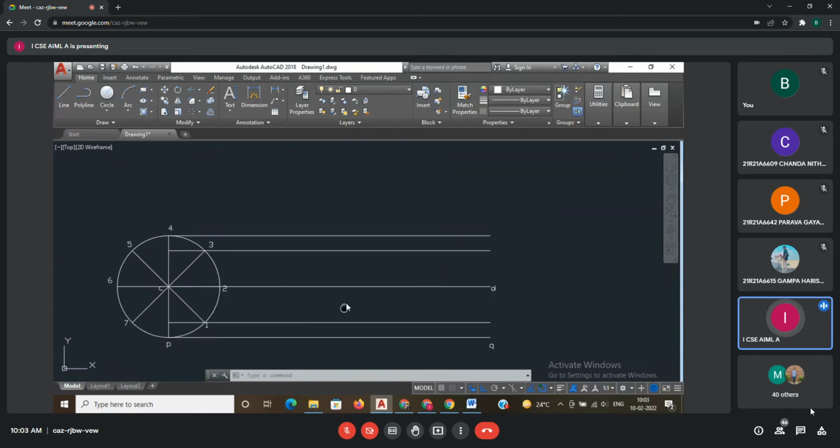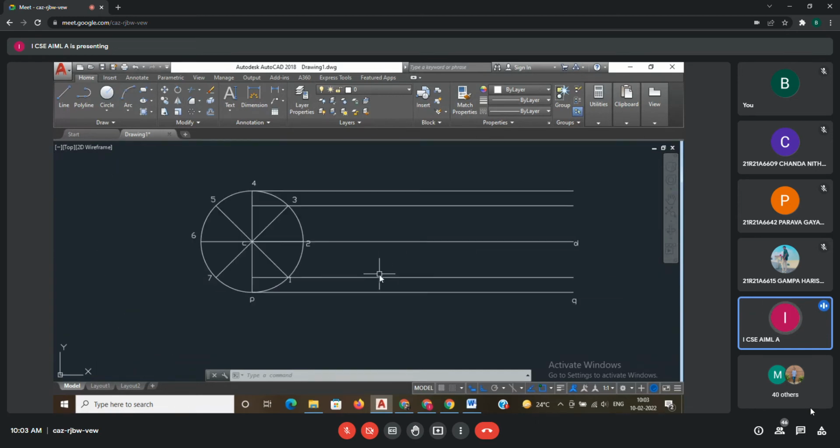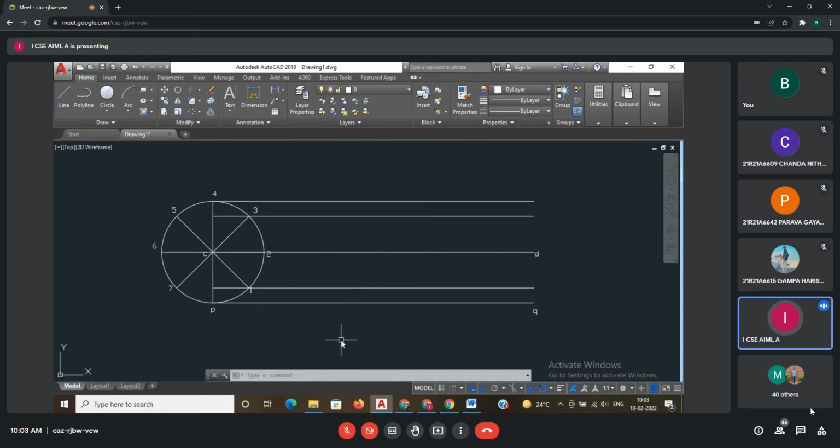Okay. Now after giving the notations, what is the next step? You have to divide the line. Which line? Baseline PQ or CD. Anyone you can divide. If you divide PQ, again you have to draw the vertical lines from PQ to CD. CD line means the center axis line. Instead of that, if you directly divide the CD line into a number of segments, it's very easy.